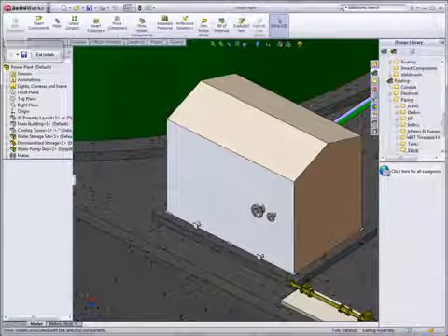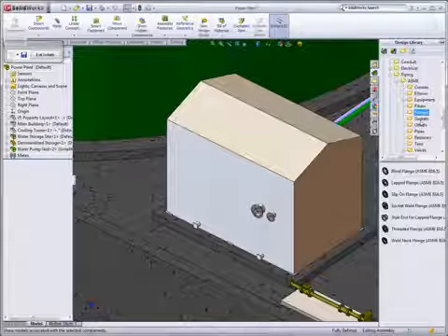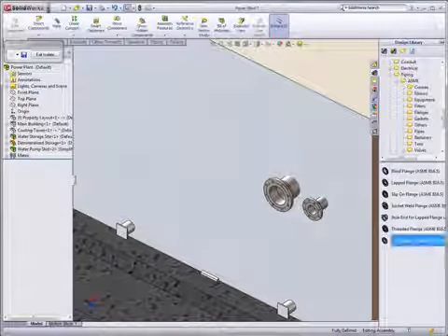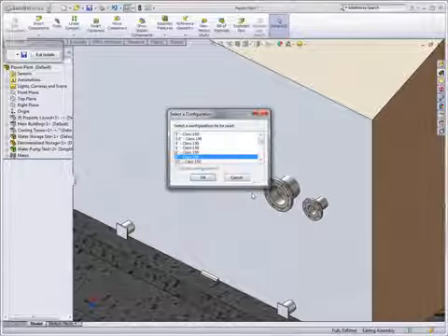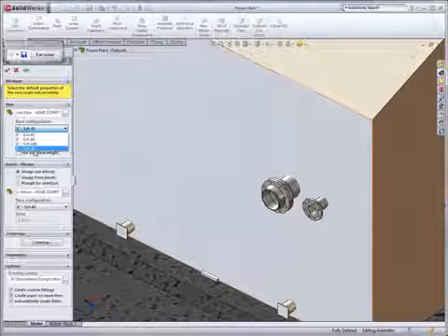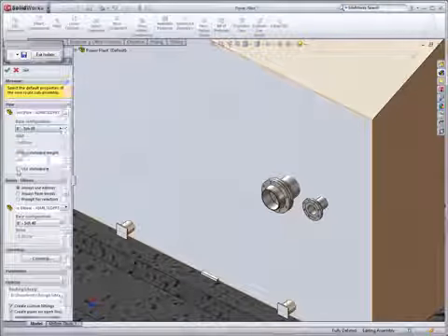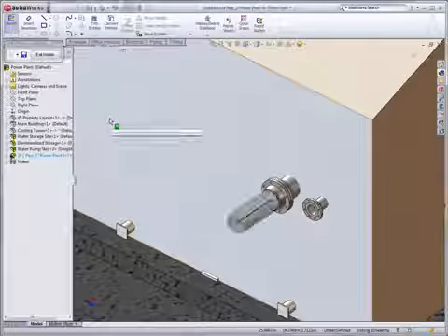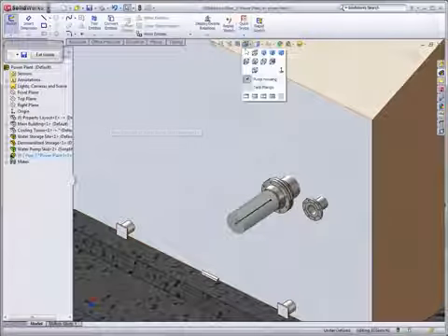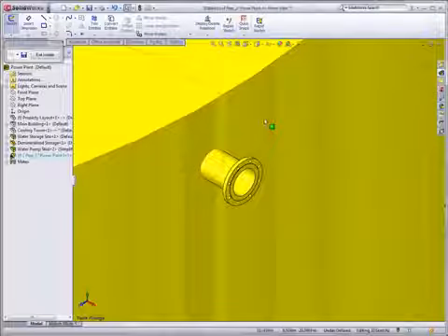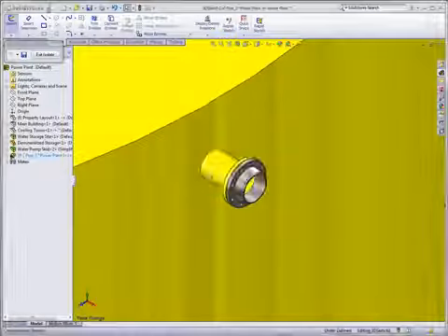Using this data in SolidWorks' piping environment, engineers can quickly snap components like flanges to one another. The models are intelligent and recognize things like nominal pipe size and schedule. We can even specify things like standard pipe lengths for generating cut list and spool data later on.